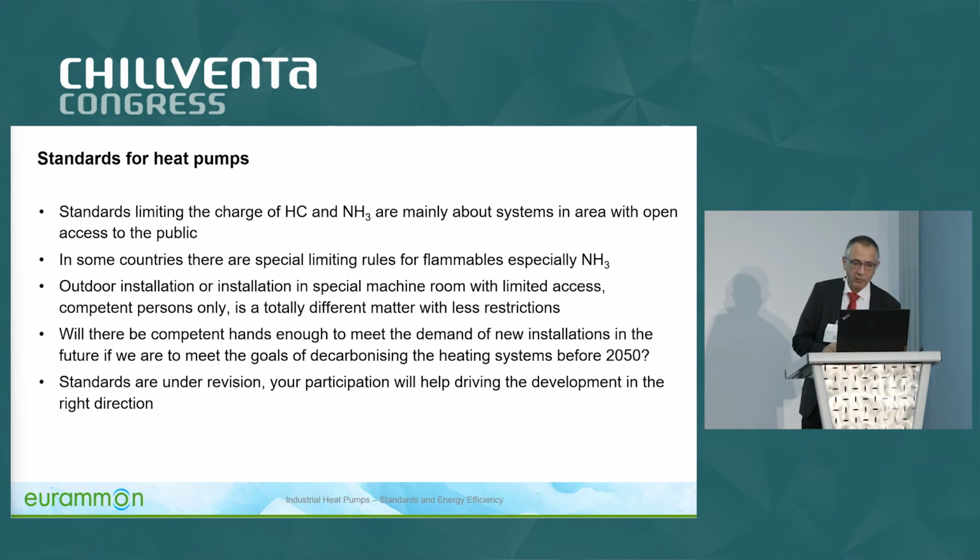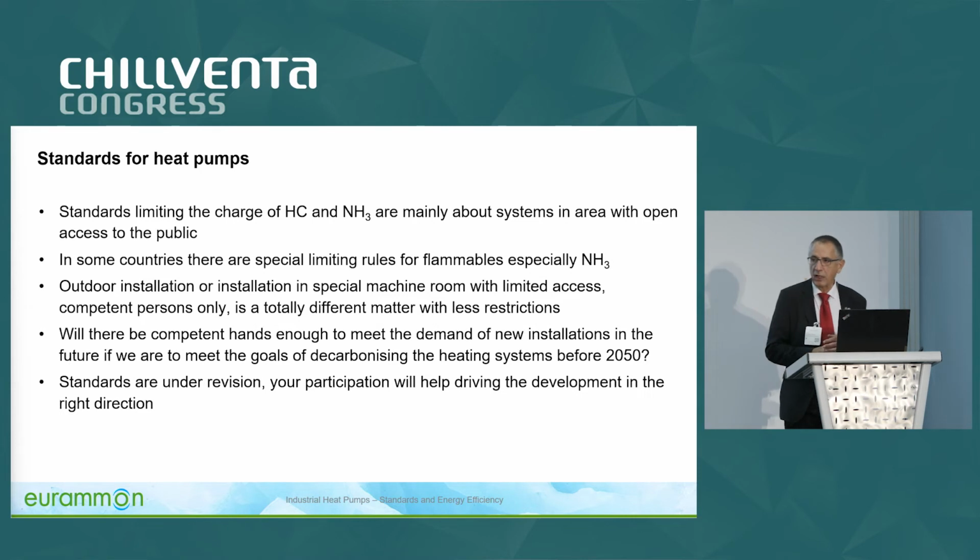So we have a lot of standards for charges. I was just talking to another manufacturer, and he was not aware that you can actually transport systems with a refrigerant charge on board. According to the ADR conventions, you can transport a system with 50 kilograms of hydrocarbon on board the chiller without any special declarations. If you go over the 50 kilos, then you have to do a little bit more documentation and advice, and there are some limits on board ships and so on. But below 50 kilos, it's nothing.